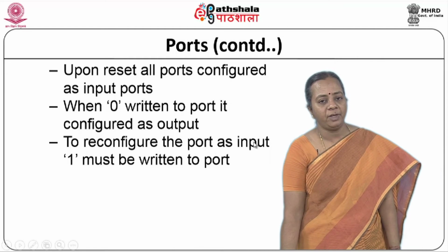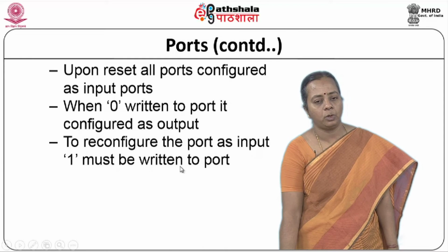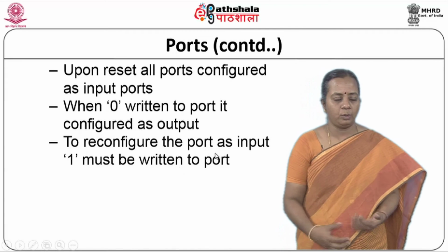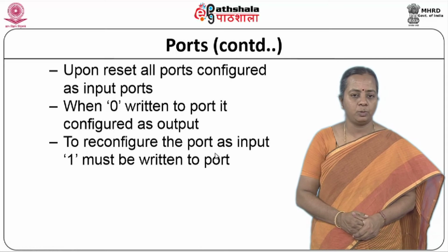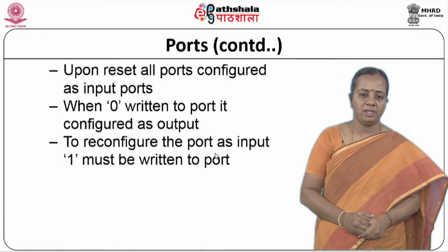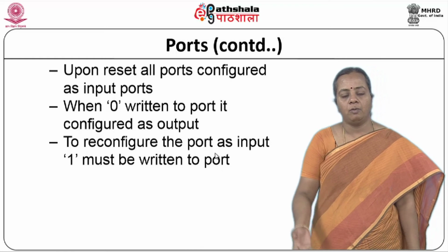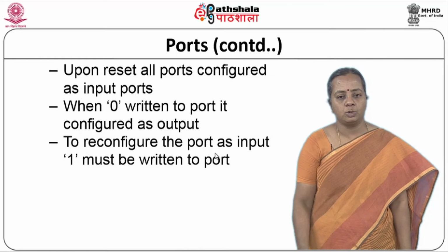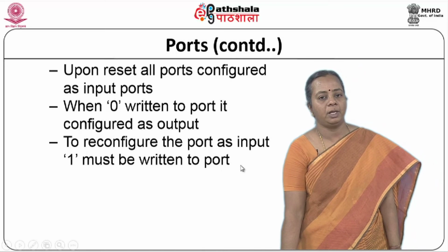If I configure the port by writing a 1 to it, then I will say that this is an input port. So, if a particular port or pin has to be used as an input for an application, then I should always start by sending a 1 to that pin or port. That declares that particular pin or port as an input pin or input port.